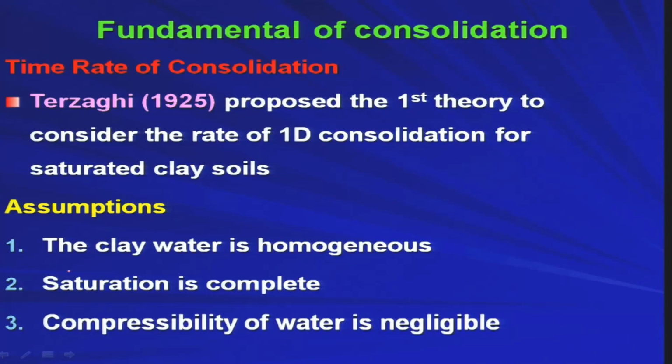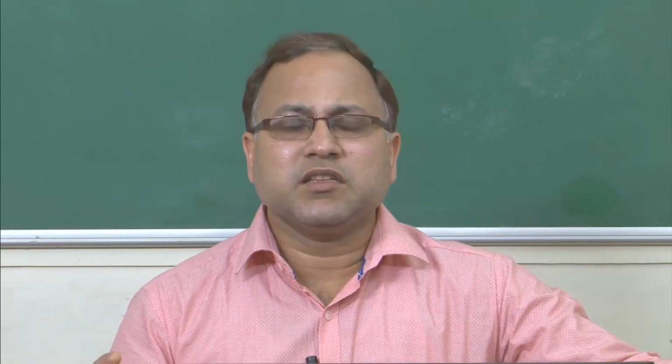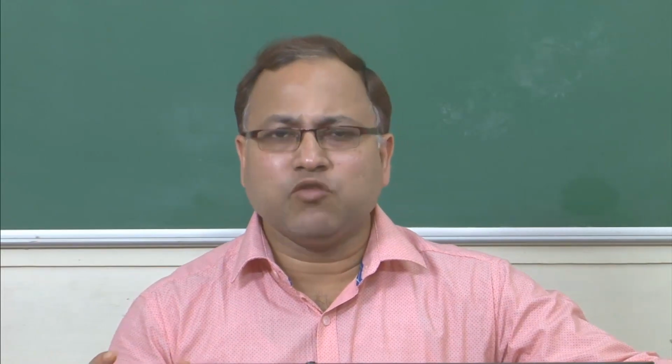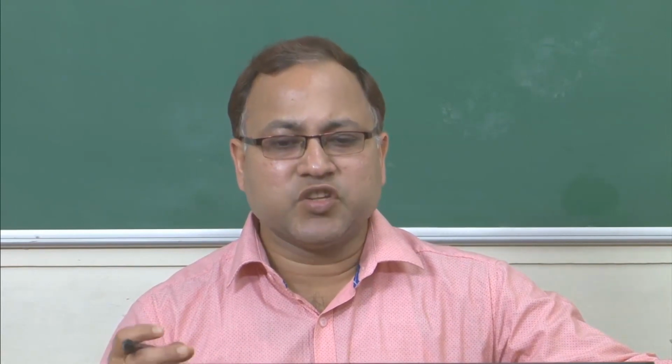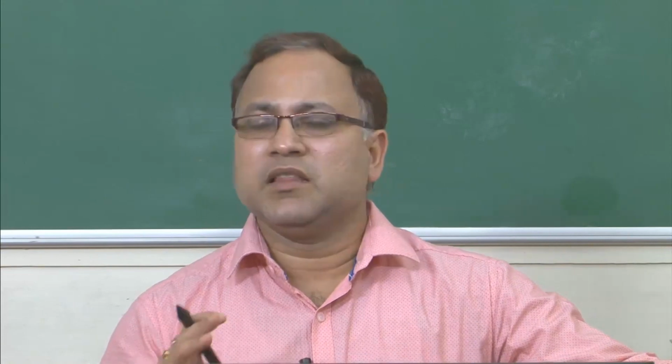Then, compressibility of water is negligible. That means water is a completely incompressible material that you are considering, and that is a good assumption. We know from mechanics that water is an incompressible material, and therefore, if we neglect the compressibility of water in the consolidation theory, there will be no harm.